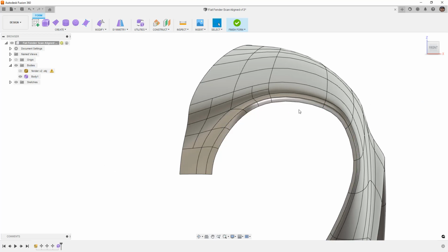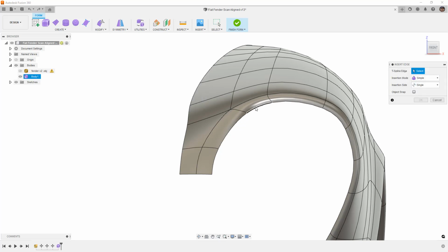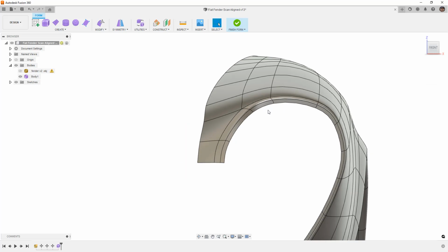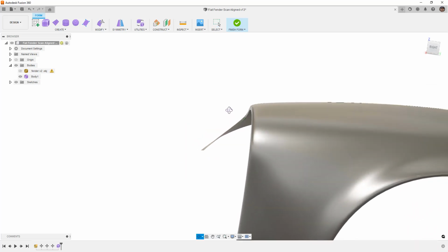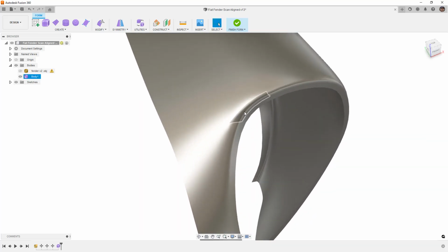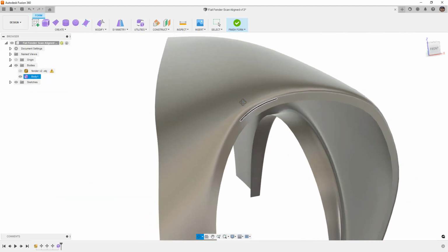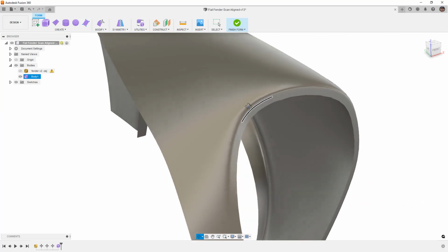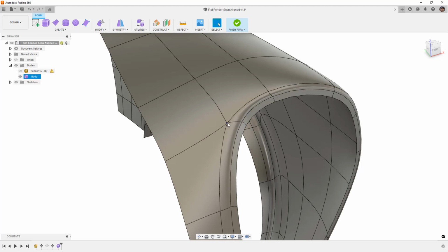And actually, let's go ahead and undo, because I still had exact set for this. I want to use simple. And when we do that and we hide the edges, what we're essentially doing is moving that star point around. And while it can work, again, it is pretty tricky. It's something that we need to be very careful of. You can't just have that open edge. You need to have more geometry, more divisions there, in order to push that star point away from the transition in curvature.